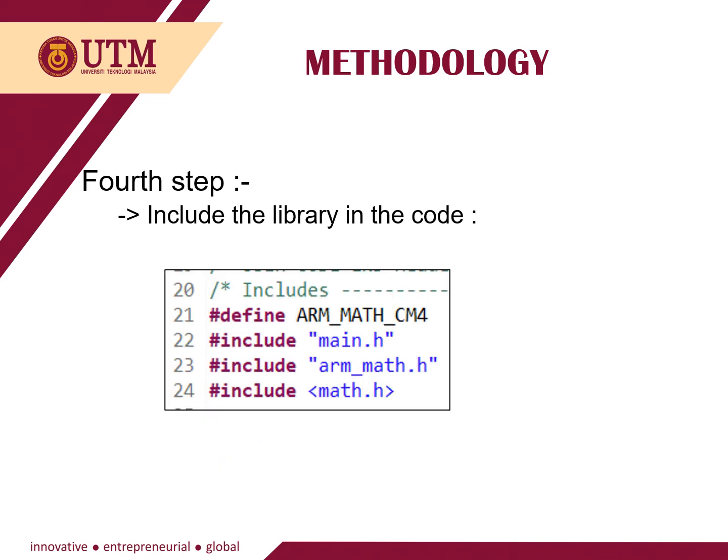The fourth step is to include the library in the code by using #include arm_math.h, and we need to also define arm_math_cm4.